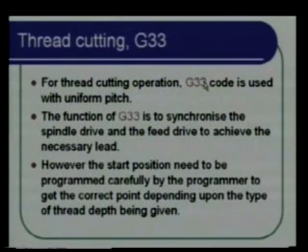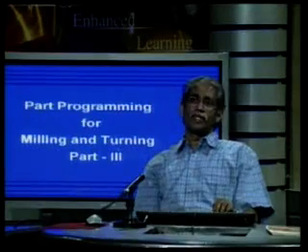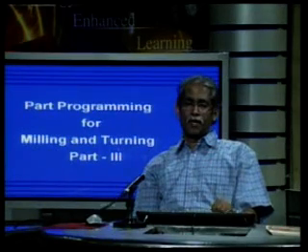Because as I said, thread cutting is identical to a normal turning operation. The only thing important to notice is we have to use a special code called G33 for thread cutting, so that it will take care of the thread chasing part. And if you are familiar with thread cutting on a conventional lathe, we will be using a chasing dial to follow. That means you will always start cutting the thread at the same point. So that will be achieved by using the G33 operation.